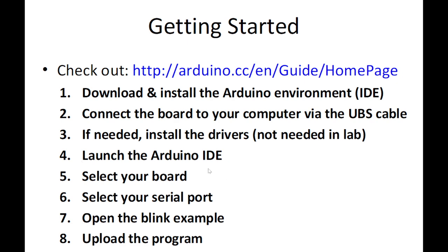Then you launch the IDE, select your board, select your COM port, and open up the blink LED example and upload the program to see the demo. Okay, so let's keep going.